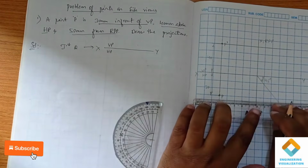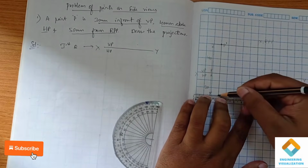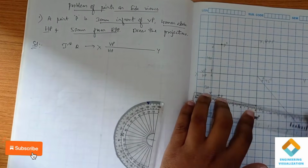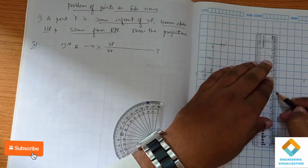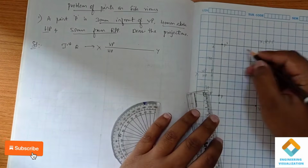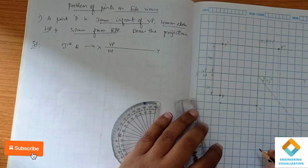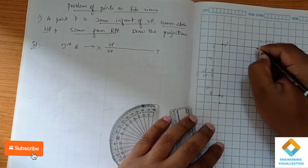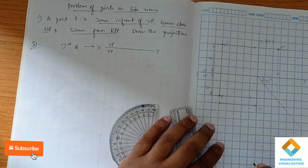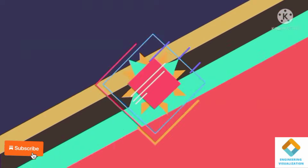Now from this top view, you draw a straight line until it touches the 45-degree line. Then we project upward. Where these two lines intersect, this point is our side view. We can show the direction of the projection line. So this is the side view.